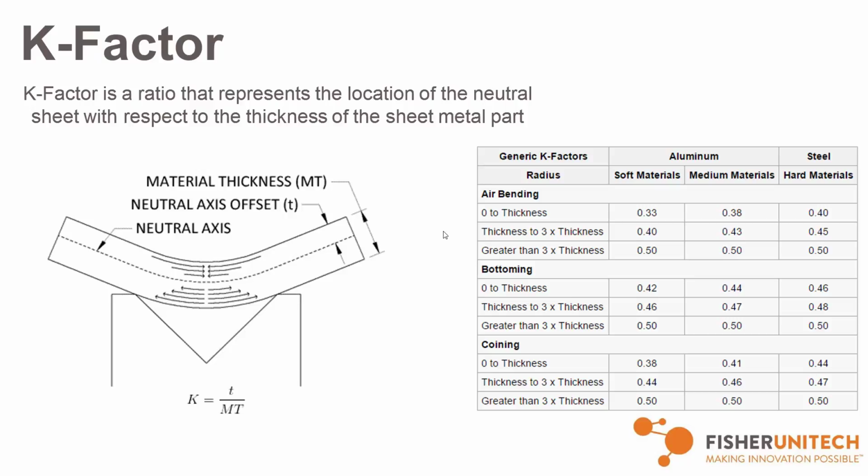So that's just a decimal, relating where that point, where no compression or tension is happening, sits with respect to the thickness. This is one of those things that starts to change depending on the material, and I guess the thickness of the actual material as well.